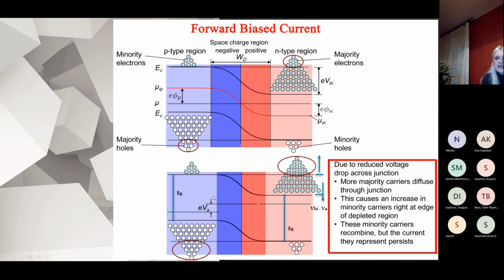And to get the ideal diode equation, we're going to calculate how much current we have, because we now have a shift of a much higher number of electrons from the N-type region to the P-type region. Completely, the same will be the story for the holes. So now this diffusion of the holes, the diffusion current part, because the higher concentration of the holes participating here will be higher than the drift current